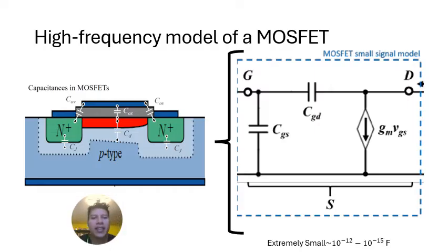when we looked at the geometry of our MOS transistors, we had this conducting layer on the top. This conducting layer would accumulate charges, which would cause an electric field, and that electric field would lead to the generation of the channel.